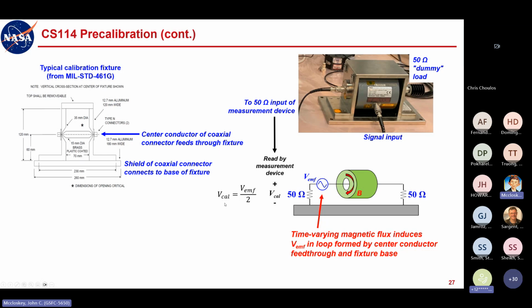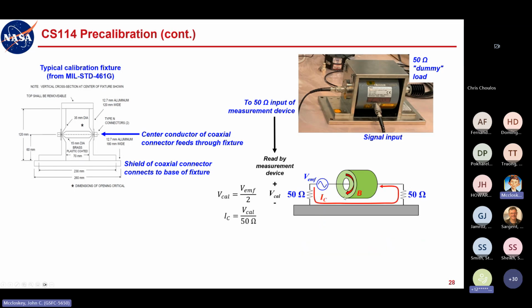Okay. So the device is generally measuring in terms of voltage, or maybe in terms of power if it's dBm, but whatever the case may be, the injected current is flowing in a loop. So these 50 ohm resistors, you need to think of them as being in series, because they are.